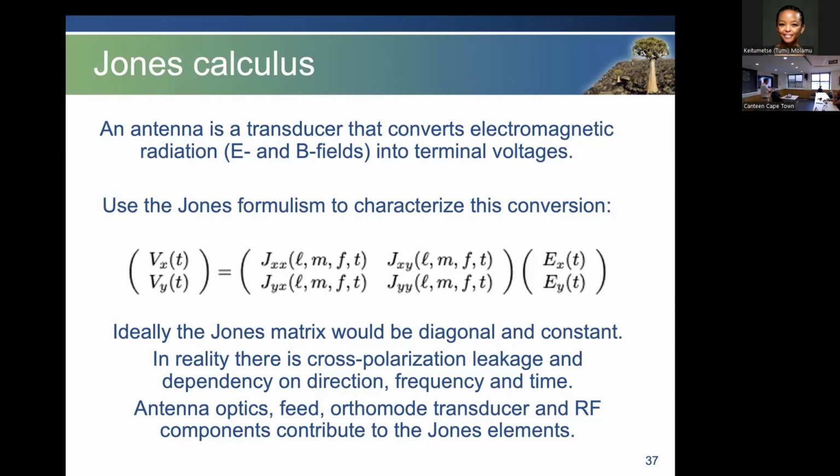And then you measure antenna voltages coming out of your antenna. You've got an X plane and a Y plane dipole, which pulls those 2 things out. And this is the Jones formalism for describing these things. Now, all of these quantities here are complex valued. They're not real numbers, they're complex numbers. You have to sort of get your head around this, because you can say, how can the E fields be complex? They're not, they're real. You measure an E field in volts. Volts is a real thing.